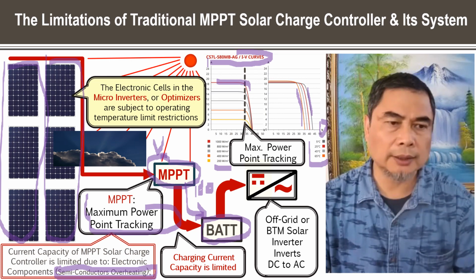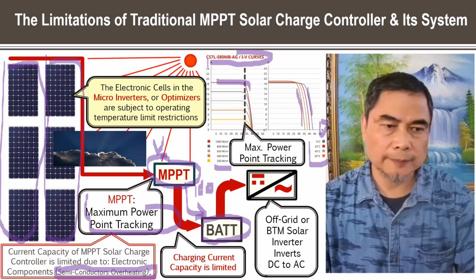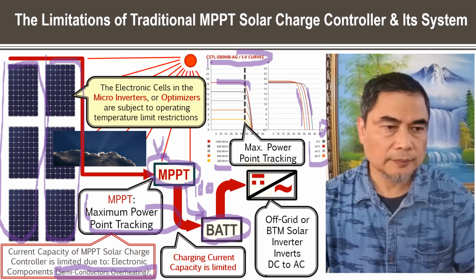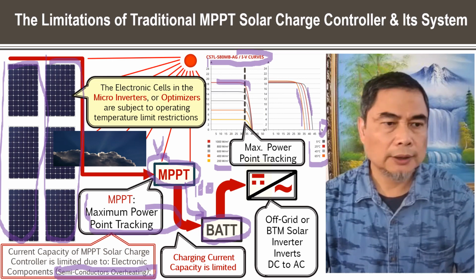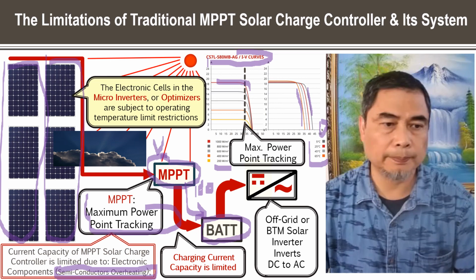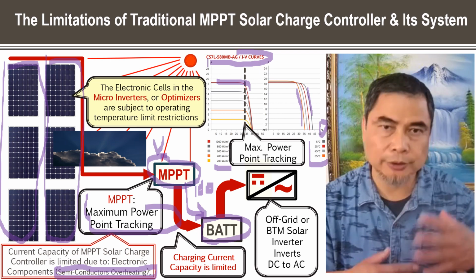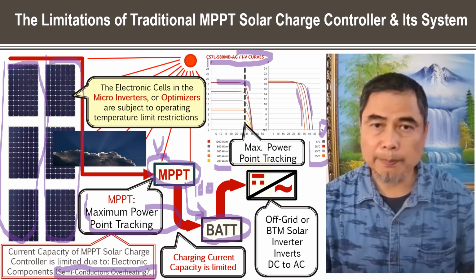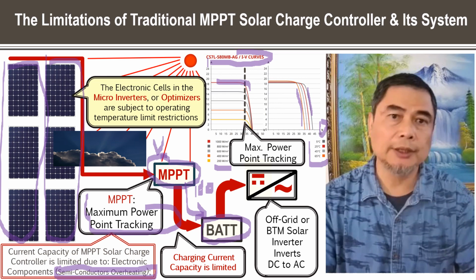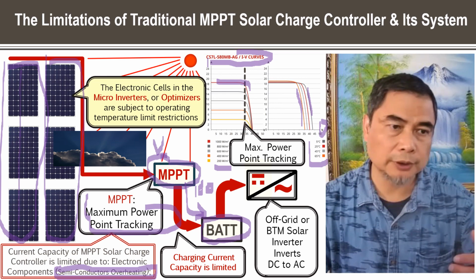And another point we want to make is that the solar panel manufacturers try to overcome the shading factors on the panels. If you connect too many solar panels in series, say one panel is covered by a cloud and shaded, it affects the whole string, because the current has to go from bottom to top all the way.